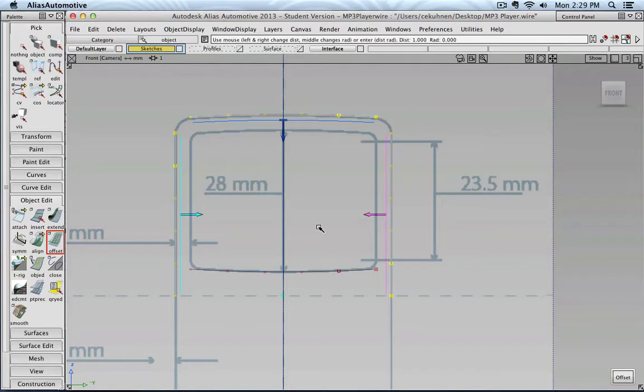And then with the left mouse button, when I click somewhere and then move my mouse left, right, I can, for example, change the offset value. But now this should be exactly 3 millimeters. Right now I have it at a distance of 3.044 millimeters.